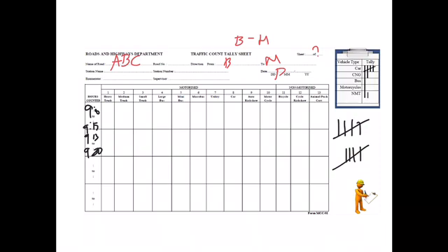Okay. So as soon as you see any two-wheeler, a motorcycle, just press 1. Car, like this. As soon as you see any category of vehicle, it needs to be marked here on the sheet with the help of tally counts. Okay, so like this you will collect the details about the number of vehicles that are passing any particular point in a road section.